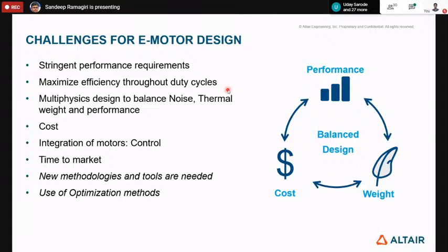And it's not a single physics, it's multi-physics. So when I say multi-physics, let me explain this. If you look at the industrial motor, most of the times we have no limitation on the space. If you look at the motor which is placed on the shop floor, we do not have a limitation on the space. We have an ample amount of space to fit that particular motor. But if you look at the electrical vehicle, we have a limitation on the space. The person who decides the layout will tell you this much space is available, and you have to target your design in the available space only. So that means we have a limitation on the space. When we have a limitation on the space, we will not have an ample amount of space to dissipate the heat.